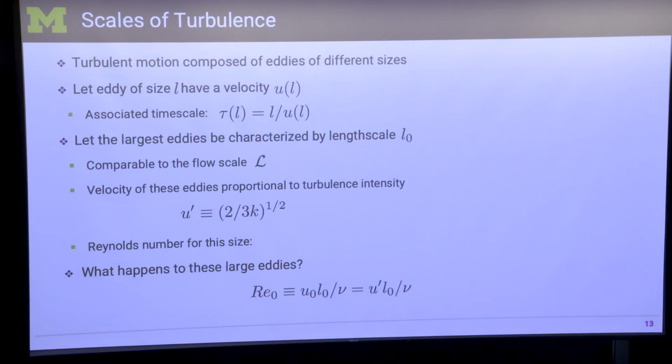So these eddies are not static. They evolve in time, and they are going to behave in a particular way, and that's what we want to understand. You can think of these eddies in terms of these length scales, and I can characterize an initial Reynolds number Re0, which is based on the large length scale, the diameter of the hurricane, let's say. That's L0. Its corresponding velocity could be U0. So U0 L0 divided by the kinematic viscosity, the physical viscosity divided by rho. So that's nu.